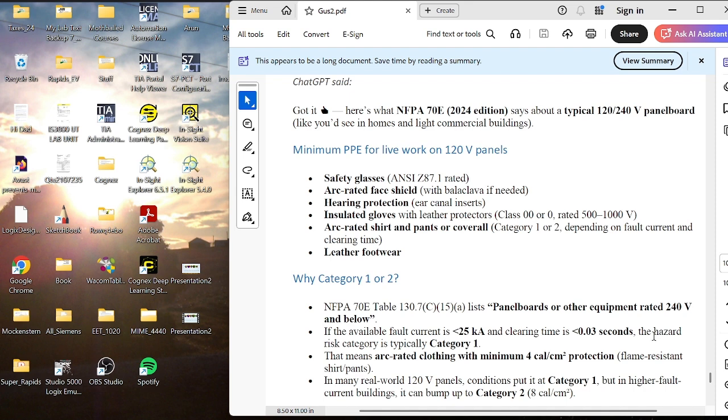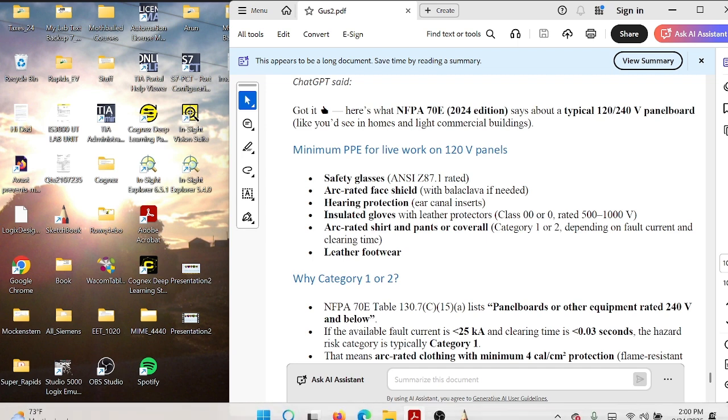Okay, all right. So do you follow now why a lot of people are switching to 24 volt controls in their panels? So you don't have to. So you can work hot, but without having to wear that clothing. So if you now look at where we're at, I think a lot of people are going to 24 volts as a control voltage. 110 has been there for years. What's the disadvantage of going to 24 volts? Well, if you've got a long run of wire from it, then all of a sudden your wire gauge might go up. So you have to calculate that wire gauge differently.